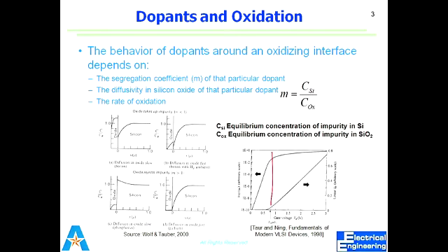It goes down inside the silicon. As more oxide grows, it consumes a particular amount of silicon, so a particular amount of silicon is consumed and a particular amount of oxide is added.